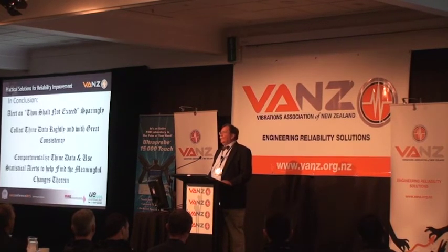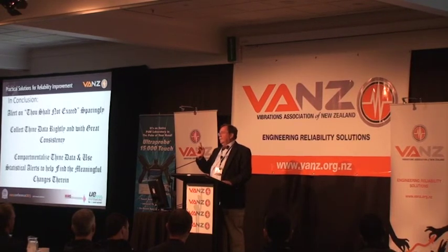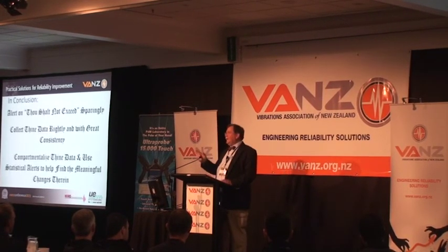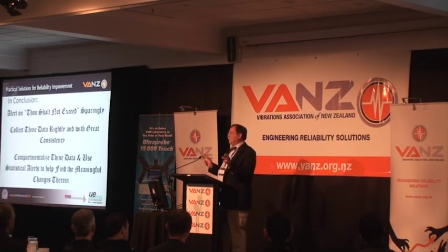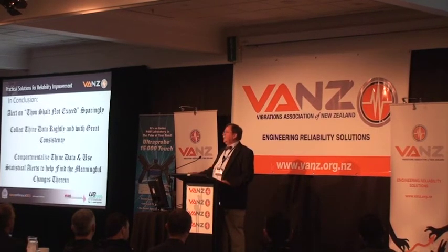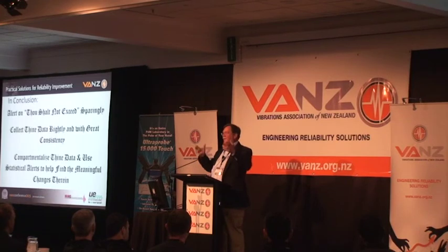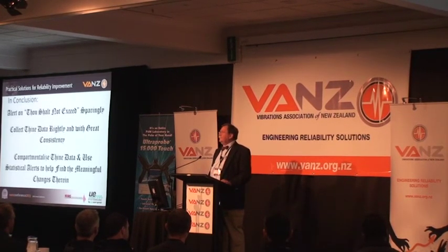The oil level too much with the sample, the first sample that came out? No, actually, both samples were legitimate. The reports were legitimate with respect to the samples that were sent out. The initial sample, everything was good. The follow-on sample, after we shut it down, we could see in the spectrum all the problems going on in the bearing. First sample was actually from a different pump? First sample, no, it was all good.